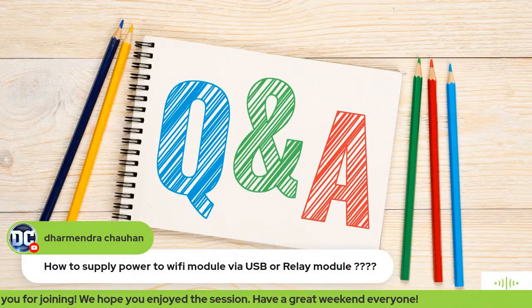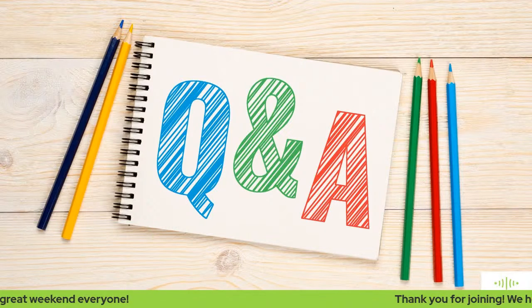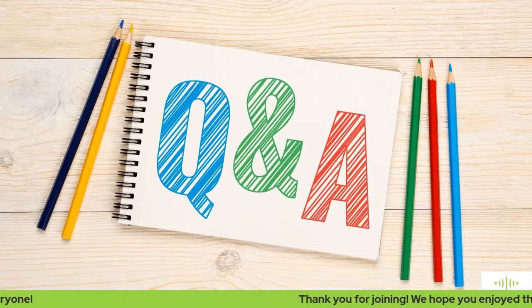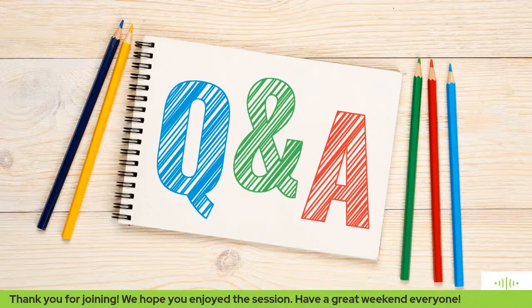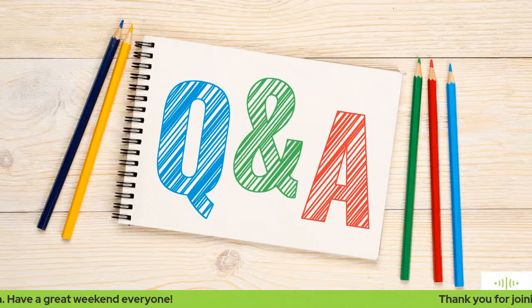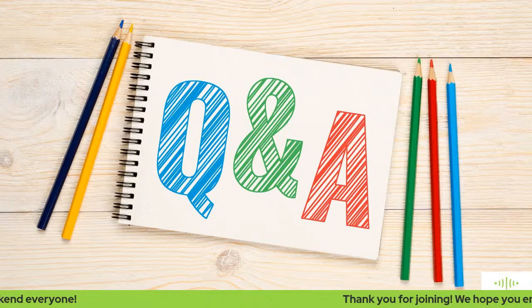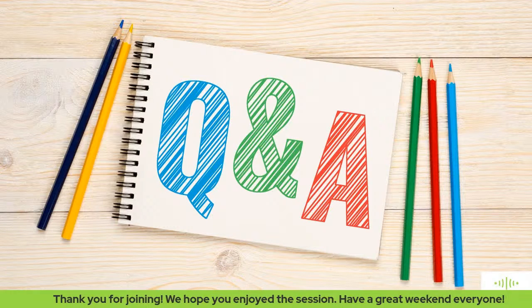All right, guys. I hope I was able to answer. How to supply power to Wi-Fi module via USB or relay module? Via USB, you can power it using a power bank or mobile charger. If you want to power the Bolt Wi-Fi module using batteries that are available in market, you can connect them to 5 volt and ground, and your Bolt Wi-Fi module will power on. For more information on this, you can visit Bolt documentation. This step is already mentioned there.